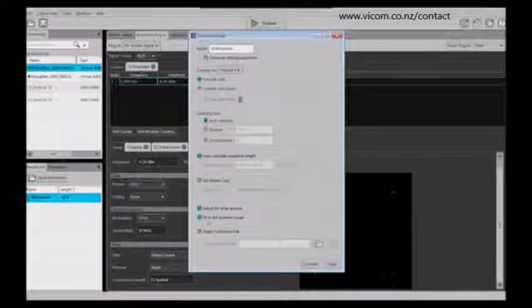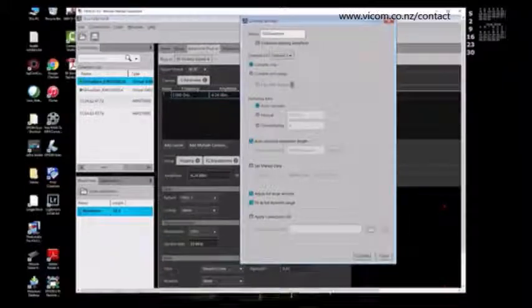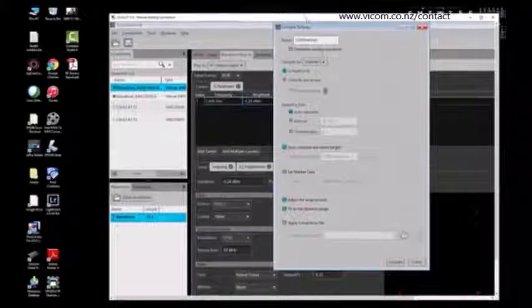We normally want to fit to the full dynamic range of the DAC, so most times you want to use the full DAC range. This will affect your amplitude settings depending on the actual AWG that you're using and what your dynamic range is, so you have to take that into consideration. We also have the capability, when you compile a waveform, to use the correction file that you created using the pre-comp utility that I showed you earlier. So this gives you complete flexibility for using this correction file. This is very useful.